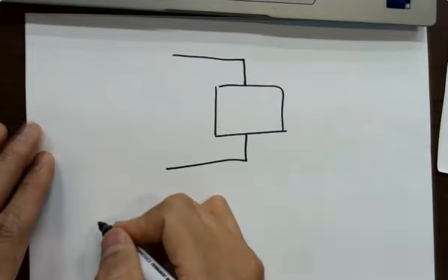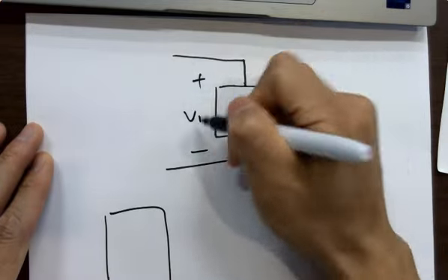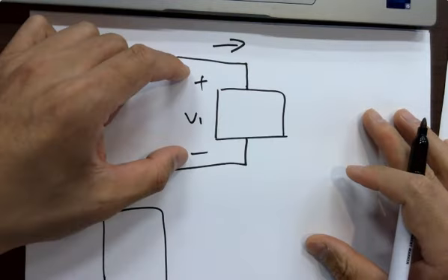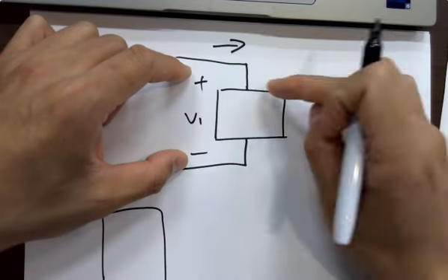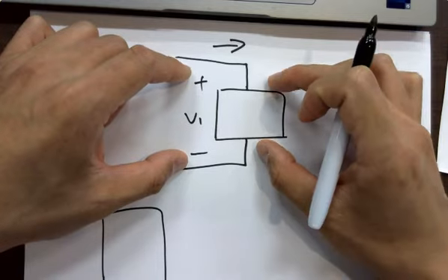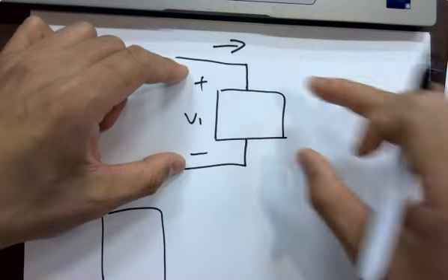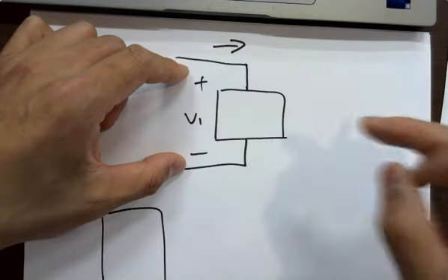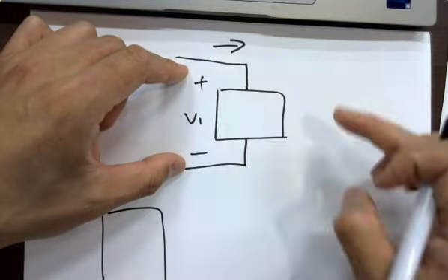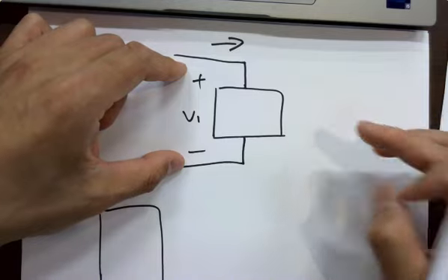So if you look at the table, here's the device, right? Plus minus V1. If I label plus minus, is it necessary that the voltage is dropping from here to here in the real world, on the circuit? If I labeled it plus minus, is there definitely going to be a positive voltage drop from here to here? No. Let me repeat the question.